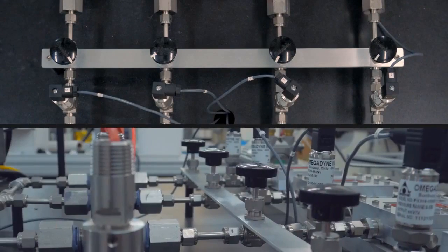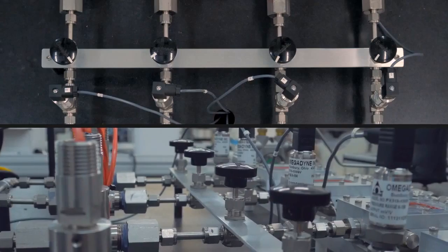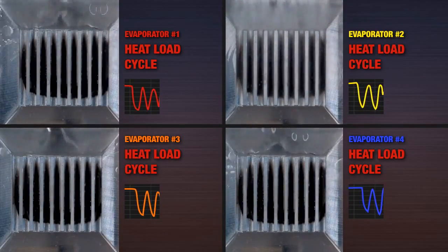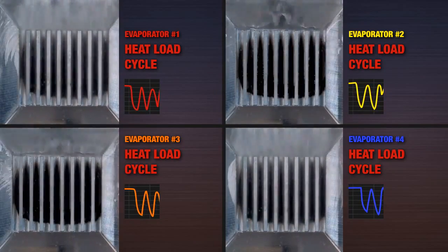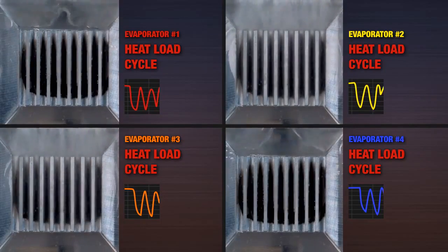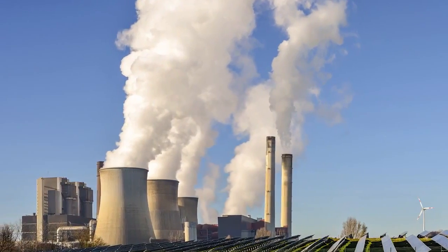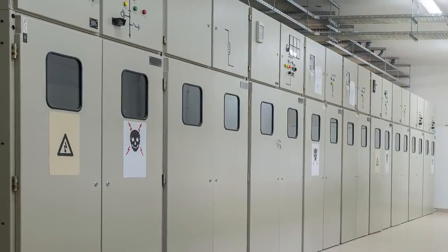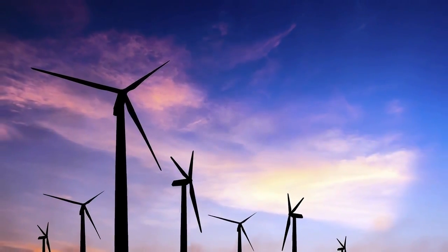With these, we can ensure that each of the evaporators receives the appropriate amount of coolant. This allows the performance of the other evaporators to remain unchanged as heat is applied to different evaporators at different times. In this way, we ensure that each evaporator provides adequate cooling to the device, as the other devices turn on and off. Not only can pumped two-phase cooling operate in an unstable, multi-evaporator environment, you've learned pumped two-phase cooling can handle higher heat loads and is more efficient than pumped single-phase cooling.